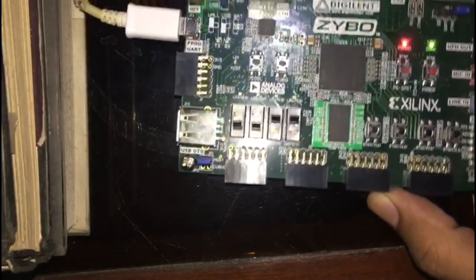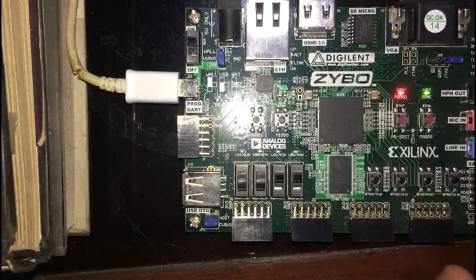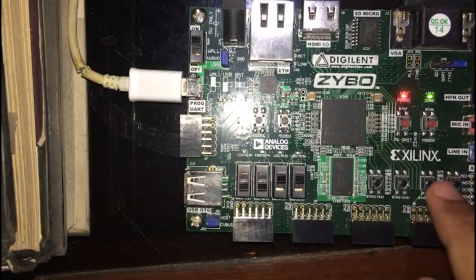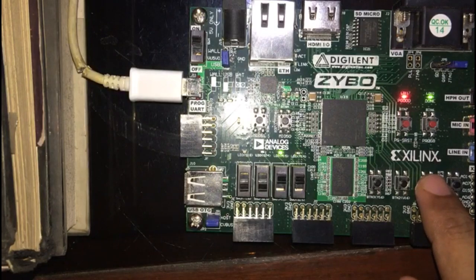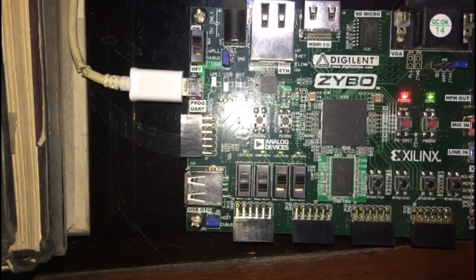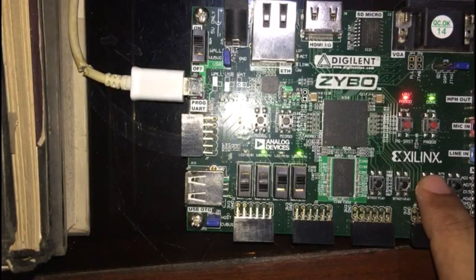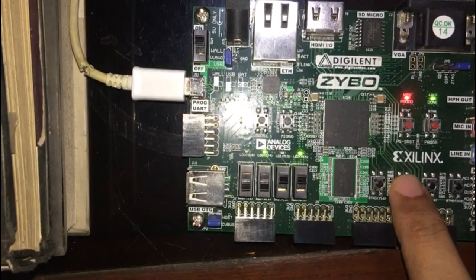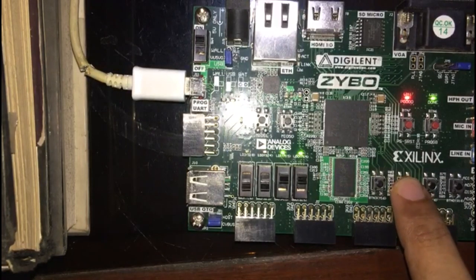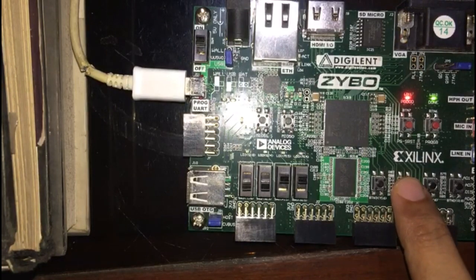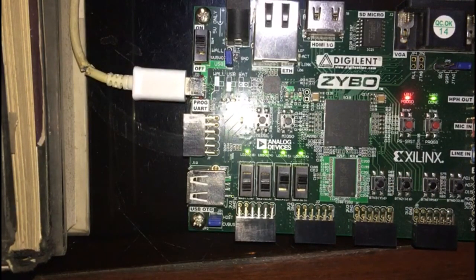Okay, so I have connected this FPGA board and programmed it. It's already reset, so you don't see any LEDs. Now if I increment it, you can see that one LED is on. So this is 0001, and then I increment it twice. I get 2, then 3, 4, 5, 6. Meanwhile if I reset it again, I get 0, and again I can increment 1, 2, 3, 4, 5, 6, and I can also decrement it using the third button, from 6 to 5, and 4, then 3, then 2, 1, and 0. And obviously if I decrement beyond 0, I get -1. It's all ones, so if you understand 2's complement numbers, it's -1.